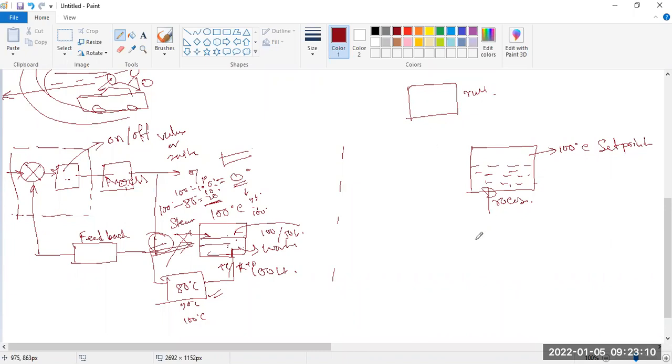Say this rule, what is it saying? If 100 liter water is there, we need the temperature of 100 degrees centigrade. That is quantity, that is temperature, meaning process value, and that is time. Say we are applying for the time, and it needs say 10 seconds. Then steam flow, this is our steam flow. This is the manipulated variable or input. This steam flow will be 10 seconds.